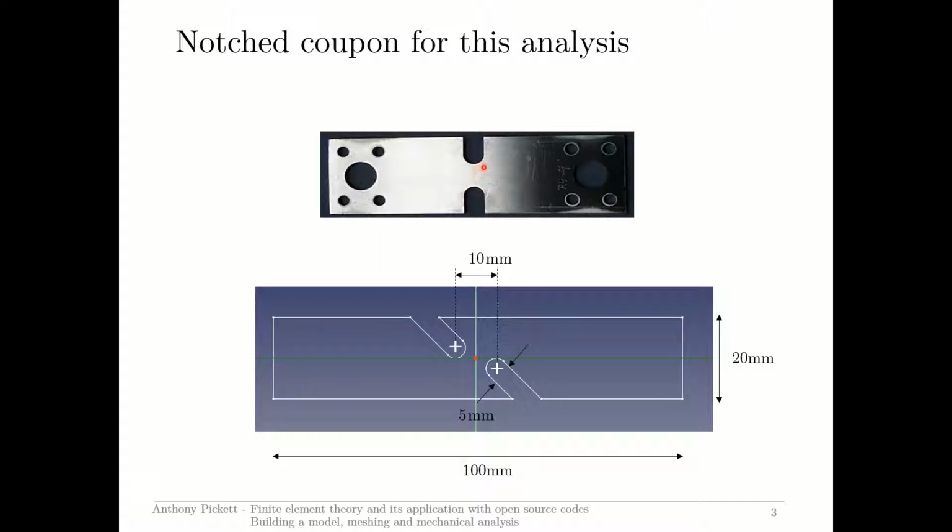And the idea of this particular specimen is that you'd essentially have a mode 1 normal stress created here and failure. This would be one coupon. And I think you could imagine you can have other coupons with notches that would be offset. And such notches would create a combination of normal and shear stress failure. And this is another notch, just a CAD drawing of a notch, where we have, in effect, pure shear being created along this line here.